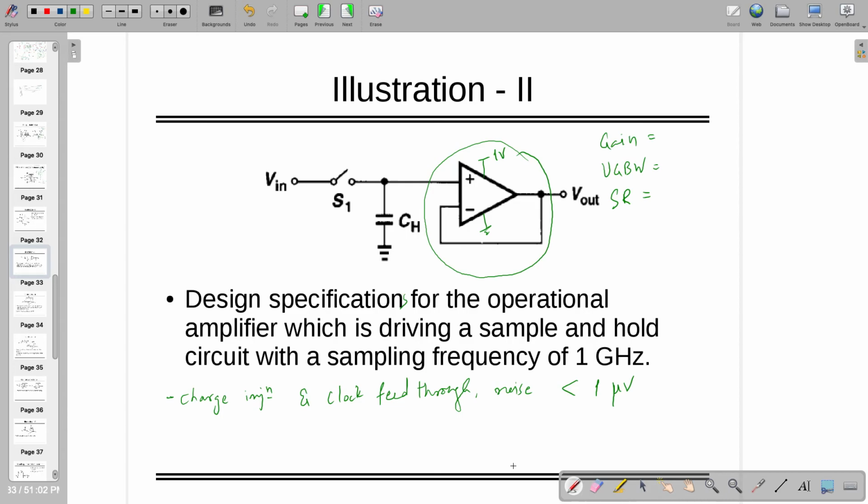Right now it's a voltage buffer, by the way, right? So what is going to bother you, that if there is V in here, same V, I'm drawing sample, so sampled is basically symbolized with star. V in star is equal to sampled input. So I want V in star here. How much can I tolerate? 1 microvolt. So how much gain do you need?